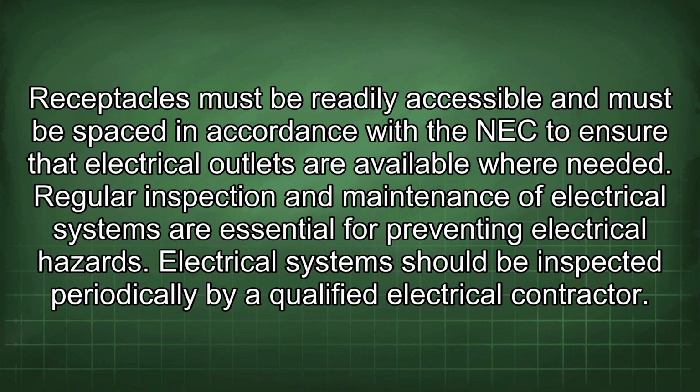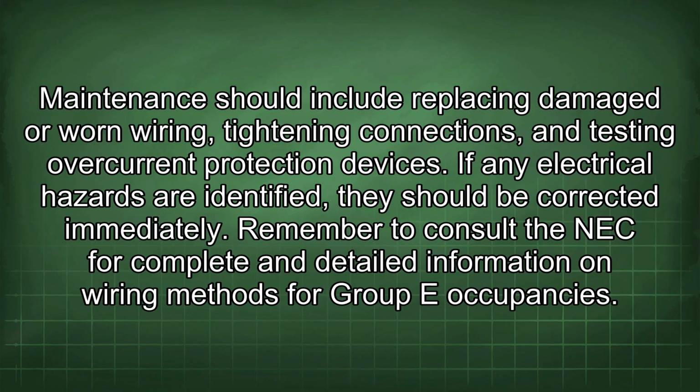Regular inspection and maintenance of electrical systems are essential for preventing electrical hazards. Electrical systems should be inspected periodically by a qualified electrical contractor. Maintenance should include replacing damaged or worn wiring, tightening connections, and testing overcurrent protection devices. If any electrical hazards are identified, they should be corrected immediately.